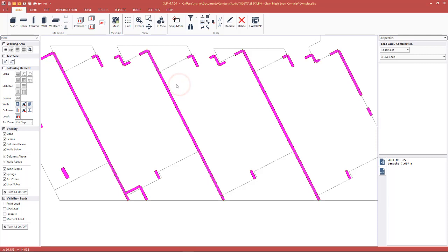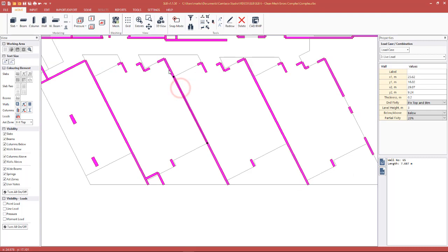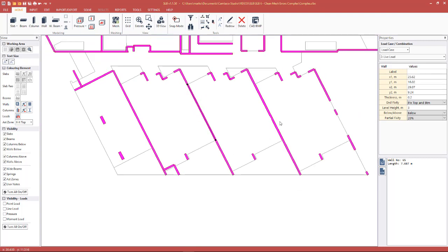However, the downside is we've segmented our wall. This option here, we've kept the wall in one piece. However, to keep this geometry, we've had to use extend with mouse and clip and use a high degree of accuracy. So again, depending on which software we're using and how important this wall is for our lateral capacity, or depending on whether it's going to be a brick wall or a reinforced concrete wall, either option may be more suitable. But definitely this option here on the left is the one that's easier to work with.